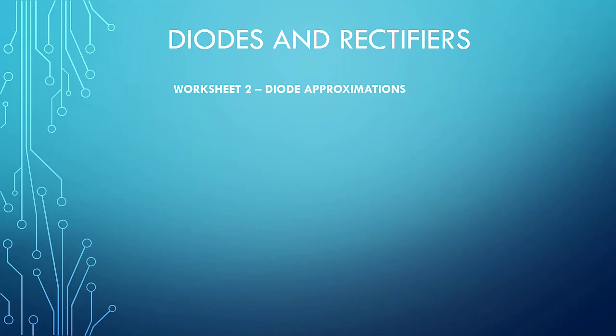There are other types of diodes we'll learn about later, like light emitting diodes. We're going to learn about Zeners here very shortly and how they act differently, but they're all part of the same family and they all have similar characteristics: forward and reverse biases, voltage drops once they're conducting, an amount of resistance and current, just like a resistor, and we can figure that out.